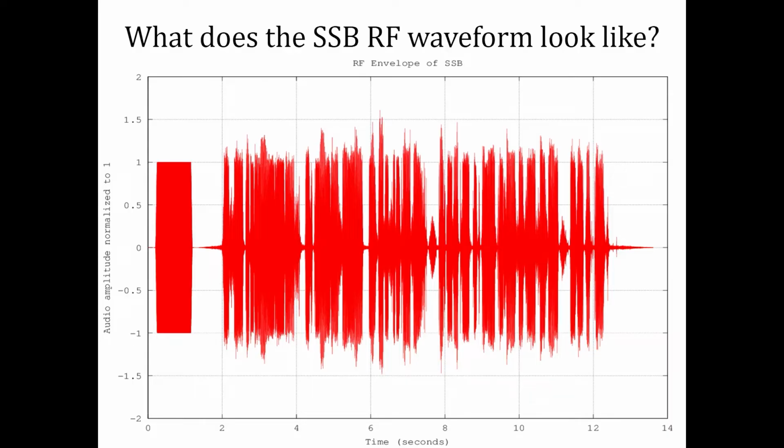The way sideband envelope overshoot has been dealt with traditionally is with ALC. We don't know what the envelope output level of the sideband modulator is going to be, so we sense RF envelope peaks and we reduce the gain of the transmit path so we don't flat top and splatter. But with traditional ALC, it's too late. The horse has already left the barn. The first overshooting RF envelope peak gets clipped, and that makes splatter. And ALC just turns down the power of the sideband signal you're transmitting.